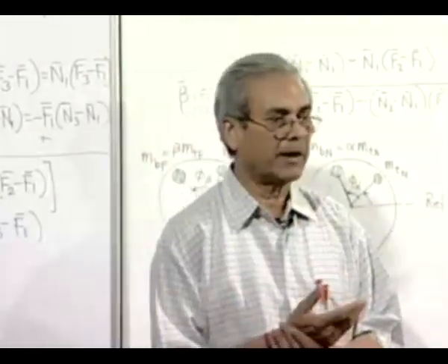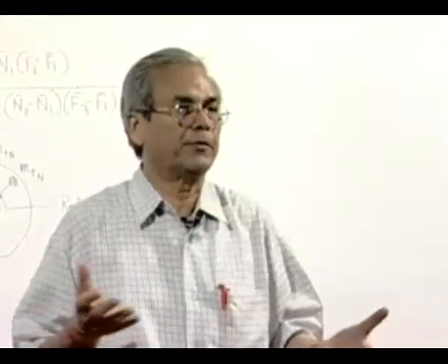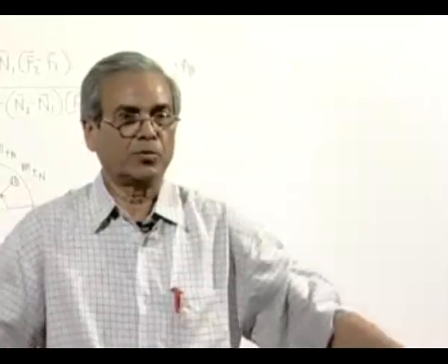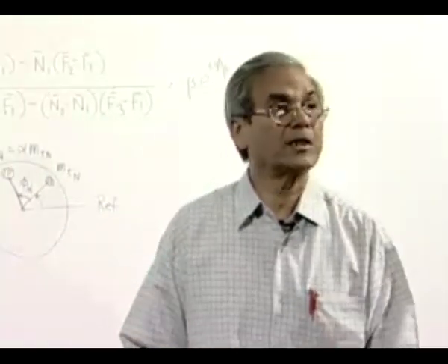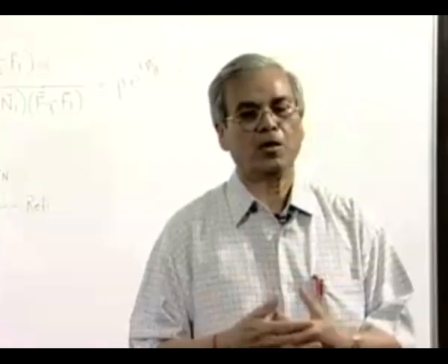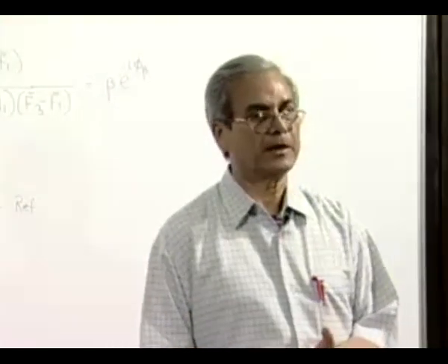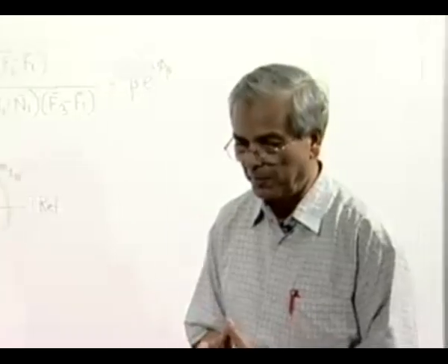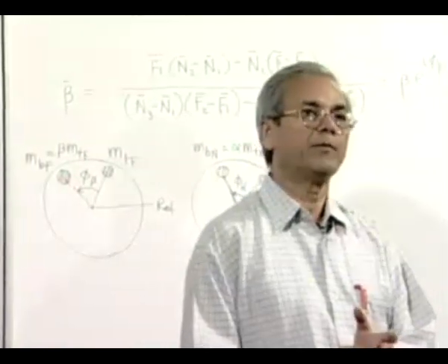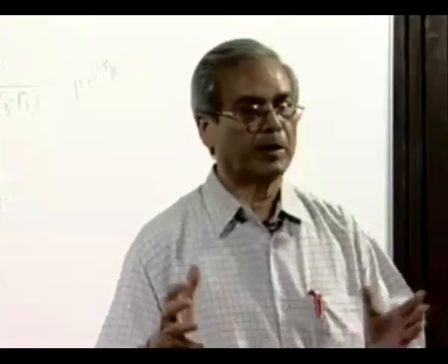The other kind of rotary balancing problem is where the mass and geometry of the rotating object are not very definite, as you find in washing machines, where we put all the wet cloth whose geometry, shape or mass are all uncertain. In such cases, a suitable technique is used for self-balancing of the rotating objects. That is also another very interesting technique of balancing rotating objects. But I think we will stop discussion on rotary balancing here, and from the next lecture we will take up the problems of balancing machines, where the systems involve reciprocating objects.